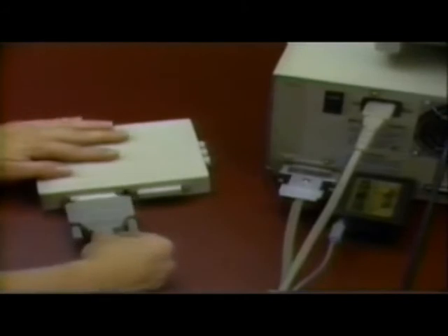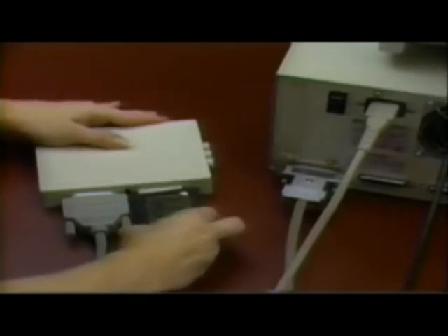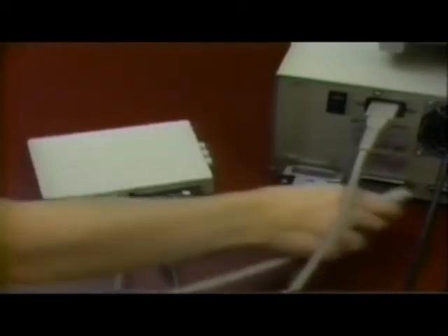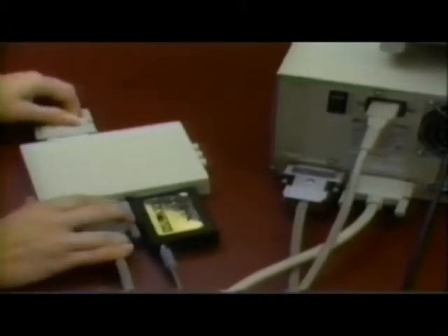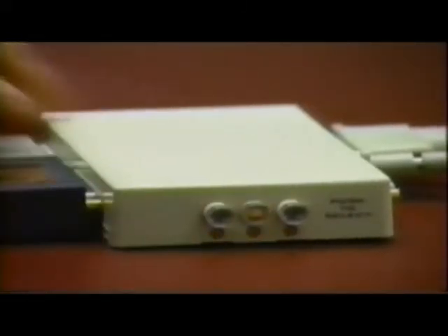The Hewlett-Packard PaintJet is a versatile and compact color inkjet printer that can produce remarkable full-color and black and white graphic printouts. The PaintJet is connected to the computer by attaching the 25-pin male printer cable to the parallel port. Since NewTek's DigiView utilizes the parallel port, a switching box can be employed to allow both devices to share the port. Connection is simple. The DigiView and printer cables are plugged into the switching box A and B connectors. A 25-pin male-to-male cable connects the Amiga's parallel port to the switching box. Select the proper device with a push of the button.